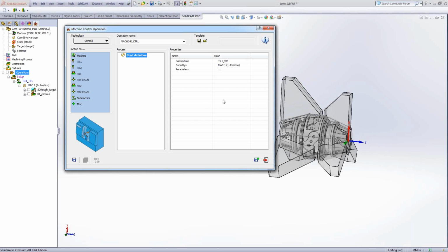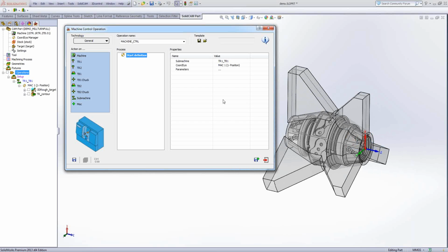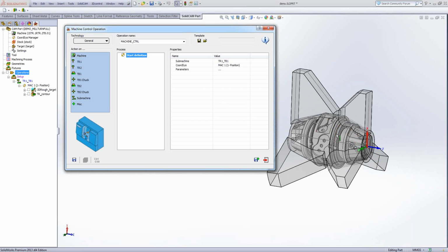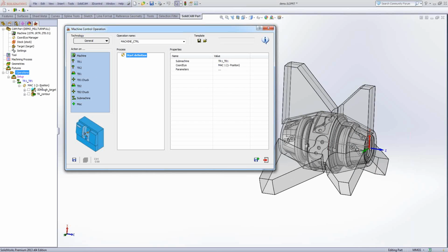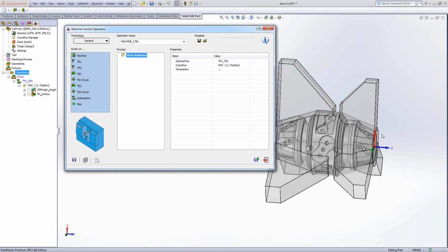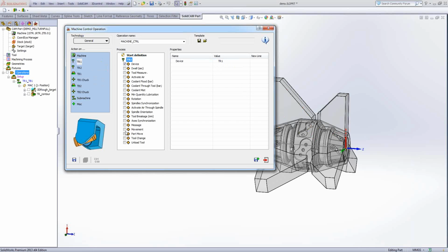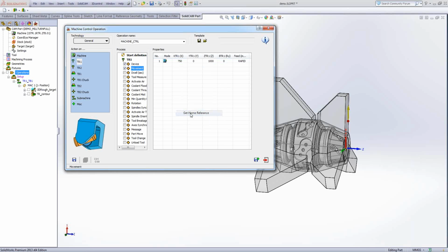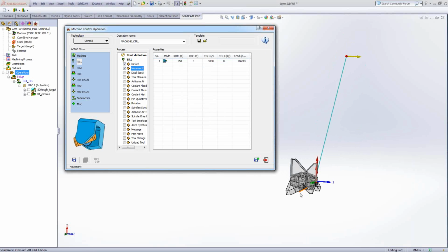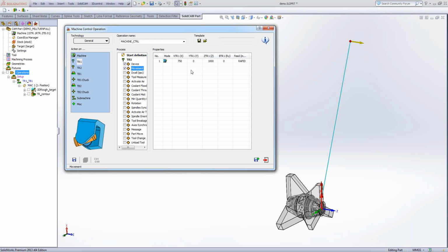So for a part transfer with rotation, first of all, we need to make a retract of turret, because turret finish the work here in the clearance plane with the tool, and now if I want to come with the back spindle and catch the part, I need to retract the turret. Retract the turret, just drag and movement, go to reference. Now you will make an interpolated movement to the reference, but I can do it axis by axis.